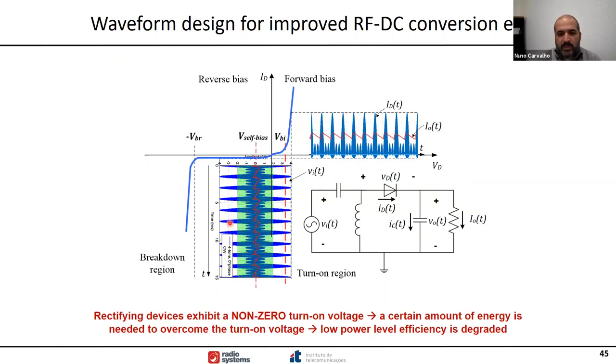So we came up with this waveform. This is what's called a multisine. So it's an addition of sines. So instead of having one sine, I have 1, 2, 3, 4, several sines, and we synchronize them all together. What that means, since we synchronize them all together, is we can create peaks of voltage with the same average power. It means that I have a huge amount of voltage, so I can excite my rectifier harder than I was exciting before.